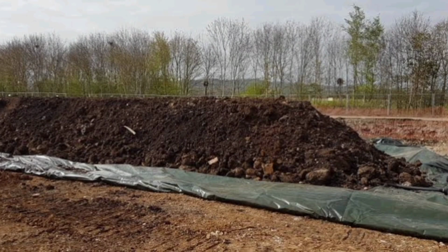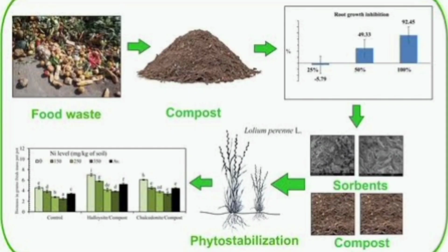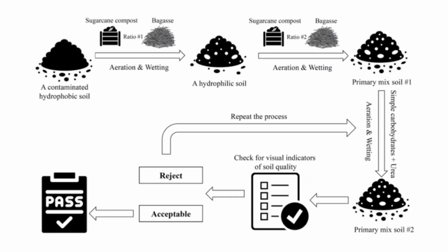Excavated contaminated soil is combined with bulking agents and organic amendments including wood chips, hay, manure, and vegetable, e.g., potato wastes. Consumption of contaminants. Contaminants in soils, ground and surface waters, and the air are consumed by microorganisms. Digestion of contaminants. Contaminants are digested, metabolized, and converted into humus and inert byproducts like carbon dioxide, water, and salts.